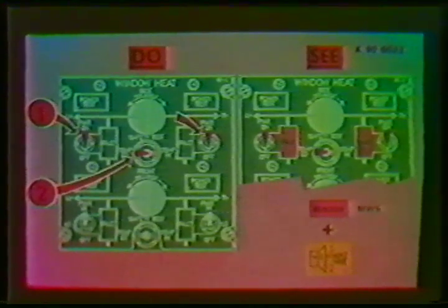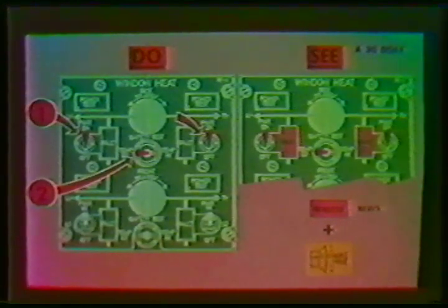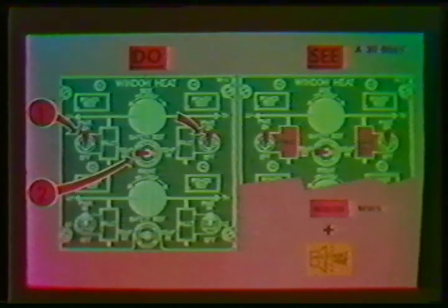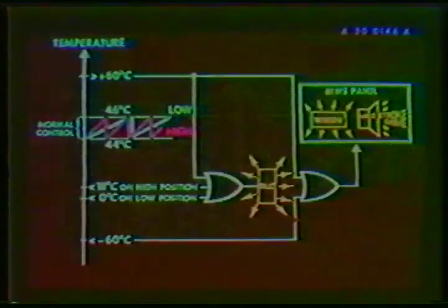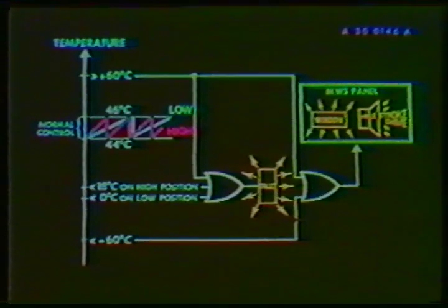The safety test switch enables us to check the minus 60 degrees centigrade low level and the plus 60 degrees high level safety features. With the power switch on and the safety test switch in the temp low or temp high position, the fault light and the window warning light on the master warning panel will illuminate, accompanied by a single stroke chime.